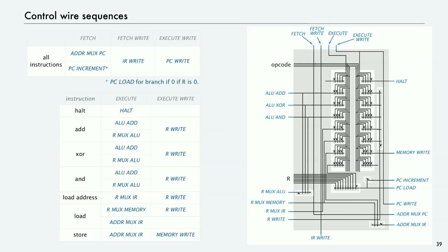A demultiplexer takes 3 bits and a signal, and produces the value of that signal on the addressed output. So the one on the left is tied in with fetch, and the one on the right is tied in with execute write. When execute comes high, it'll light up one of those 8 outputs on the left, and when execute write becomes high, one of the 8 outputs on the right will be lit up according to the instruction. So only one of those lines is on.